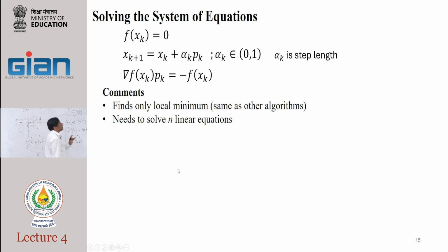So behind the scenes, at the end of the day, I need to solve the linear equation. Remember, even for Aspen AdSim, it doesn't matter whether you are solving an integration problem or nonlinear equations, at the end of the day you are actually solving the linear equation. When you see the solver in Aspen Custom Modeler, it has a bunch of settings for the linear algebra solver and a bunch of settings for nonlinear equations, but that is a completely different thing. When we go there, we'll describe that.